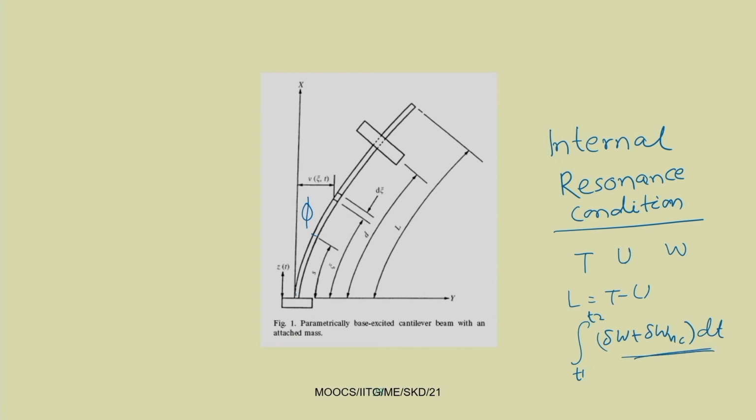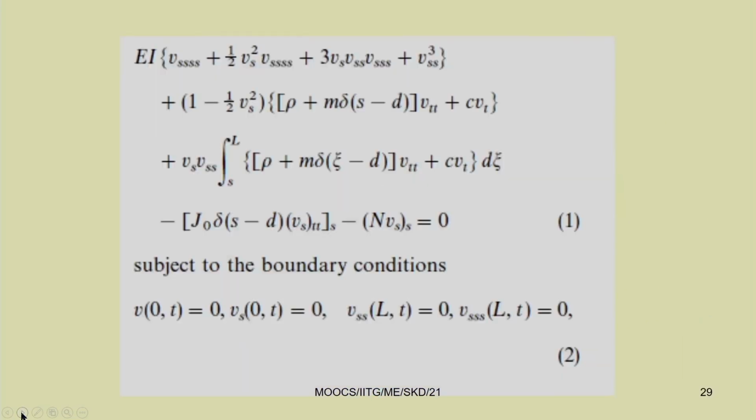The advantage of using this extended Hamilton principle is that one can get the equation of motion and the boundary conditions simultaneously. With the Lagrange principle, one can obtain the equation of motion conveniently, but the boundary conditions one has to decide later. By using the extended Hamilton principle, one can get both the equation of motion and the boundary conditions.